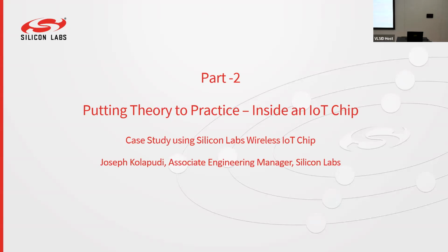You try to reduce it by deciding whether you really want that circuit to be clocked. Can you avoid clocking it? Can you reduce your clock rate? All that reduces your dynamic power. Your leakage power is based on the structure of the cells and what kind of cells you want to use, and whether you can reduce leakage power by turning off a device. Instead of shutting down the clock, can I just power down that circuit?